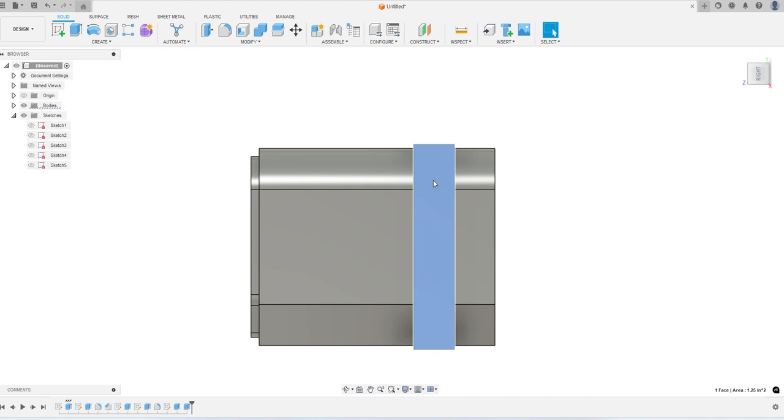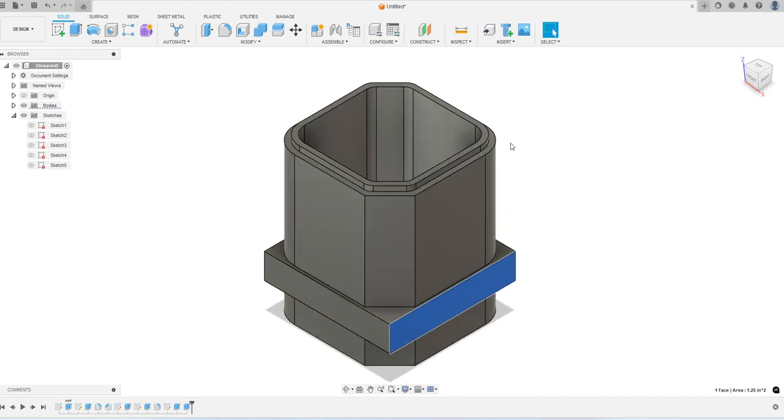If you wanted to move that, where you had a taller lid and a shorter base, that's totally okay. You just have to make sure that I have 1/2 inch of a clamping boss. We're going to mill this just like you see here, and then cut that right through the middle of the clamping boss, and we'll do a couple of facing operations to get it to be totally flat.